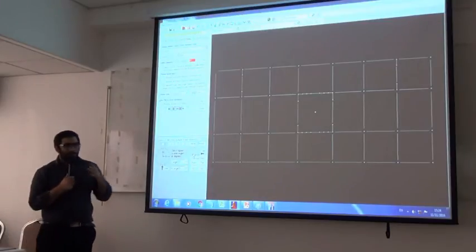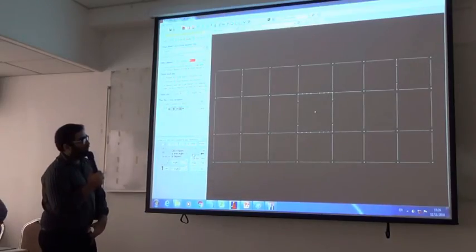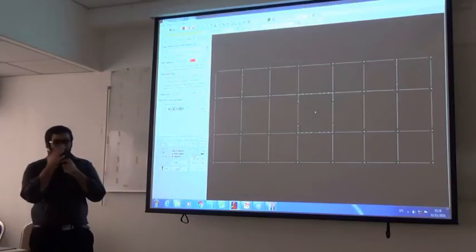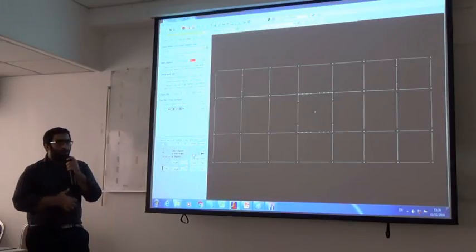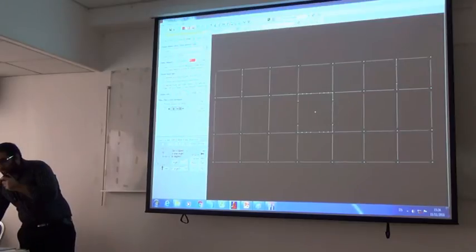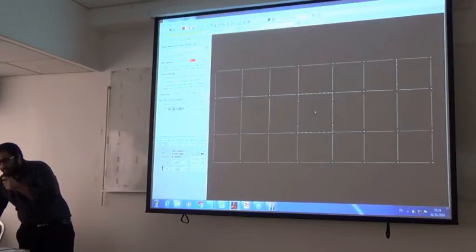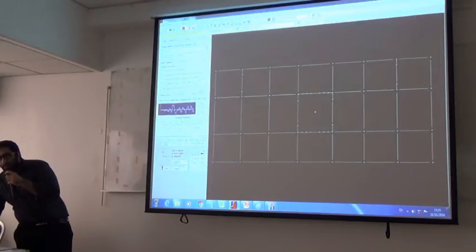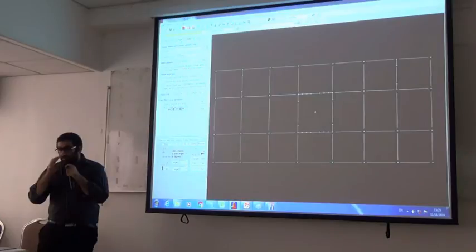This one is also something that we would like to check sometimes to see the behavior of some components or some actions that we have modeled as linear. As you remember, we modeled our columns as completely linear, right? So if you want to check the column forces throughout the time history, meaning the forces of this column throughout the height of the structure, you can use this option over here. The option is called moment and shear diagrams. It will plot the moment and shear diagrams of columns for you. You can have a single element option, or a line of elements whereby you can select many elements, and the moment and shear diagrams for all of those elements will be plotted for you.